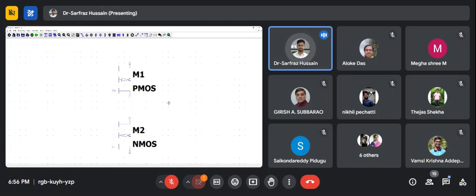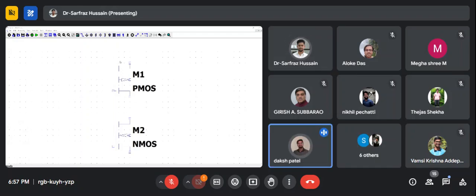I can create a circuit and then I can do the simulation. This is one thing that I can do with the LTspice tool: just creating a basic schematic and doing the simulation. Now, for simulation I have got a lot of options, so I need to show you. That's why I opened this one. You can have these settings and parameters, and you can configure what type of analysis you can do. Here you can see you can do a transient analysis, AC, DC. You can do the noise. You can do DC transfer.